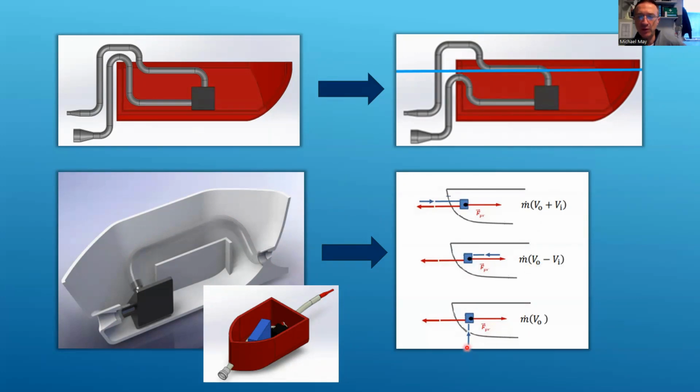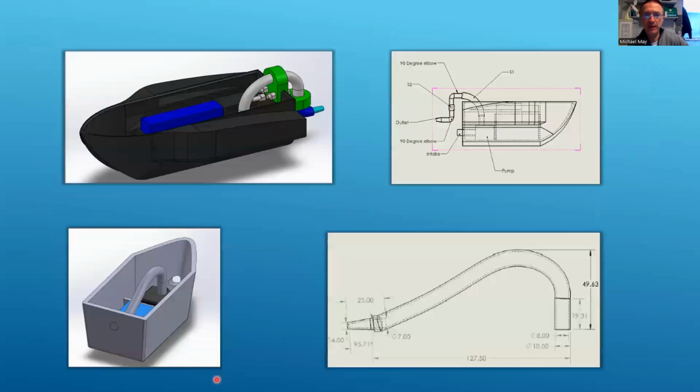And if we take the fluid straight up from the bottom and out the back, we can neglect the inlet velocity. So once again, less propulsion. So the maximum propulsion is provided by a situation where we take the fluid in from the back and expel it out the back. This feature will also add an obstruction to the hydrodynamics, and then it might push our boat off to the left or right. We've had some groups experimenting with these outlet pipe designs like this.